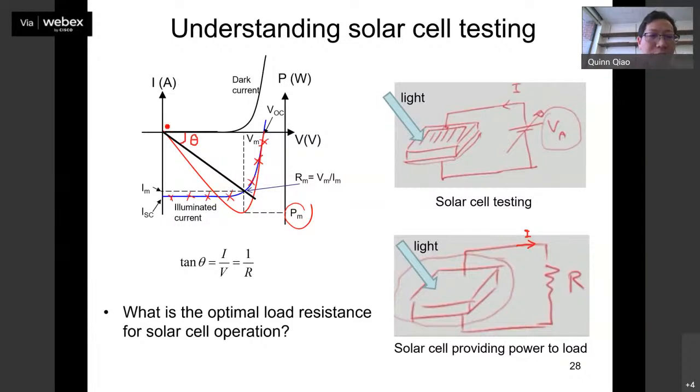You can change the V, right? The V1 is here, V1, right? Until VOC, right? VOC. And then V2, Vn, right? You change this voltage, and then for each voltage, when you change it, your current is different. That's where you figure out how you plot the IV, right? Another thing you can see, because at each position you have V1, I1, I2, then you can get Rn equal to what? At each of those positions it's Vn over In, right? And that means the Rn is different for each of the IV curve points, right? That's basically, if you change the resistance, you can also measure this IV curve.